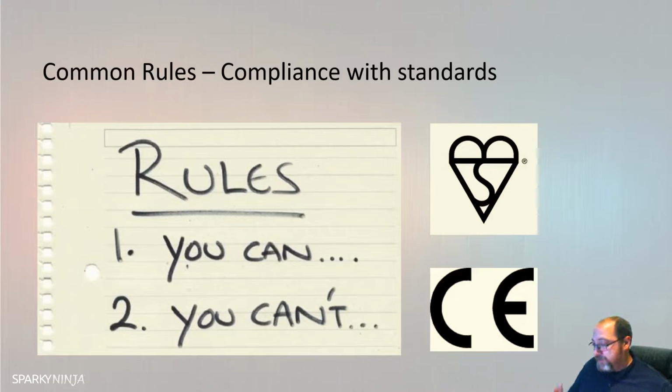The last bit there though, in other parts of BS 7671, and it shall take account of manufacturer's instructions. 511, compliance with standards. Every item of equipment shall comply with the relevant requirements of the applicable British or harmonised standard appropriate to the intended use of the equipment. The edition of the standard shall be the current edition, with those amendments pertaining at a date to be agreed by the parties of the contract concerned.